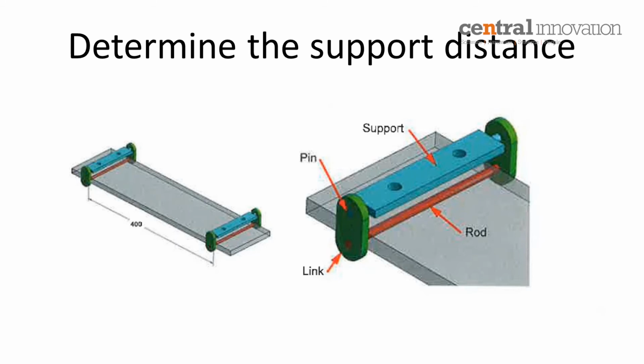So let me show that from the design, and I'm not going to use an assembly. Before I show you the setup, I'll explain a few more things. I'm going to assume this rod is a rigid rod. I'm not worried about any deformation or stress on that red color rod because it's rigid. Also, I'm not worried about the pins and the contact forces between the rod and the pin connections. I'm going to take out all those parts and use only that gray color plate, meaning only that part file. I'm trying to simplify the simulation setup.